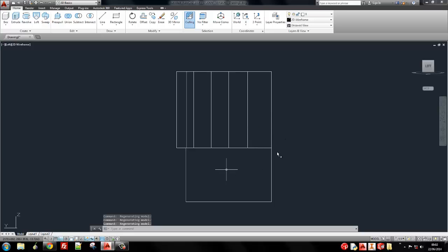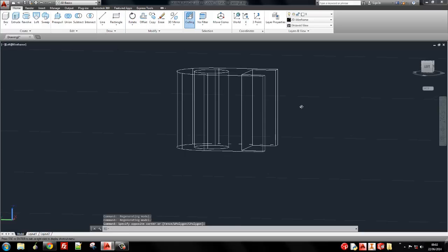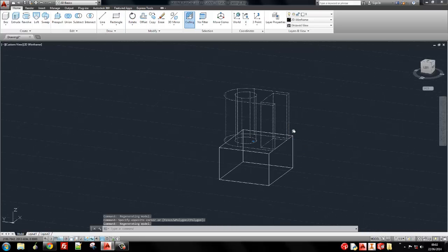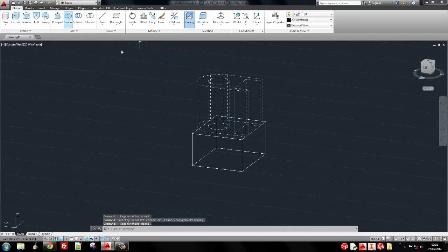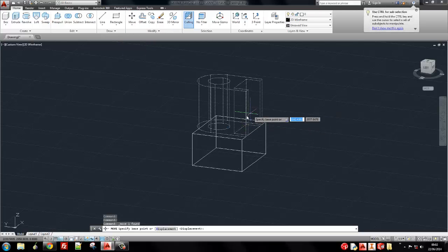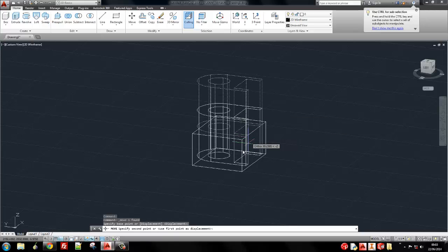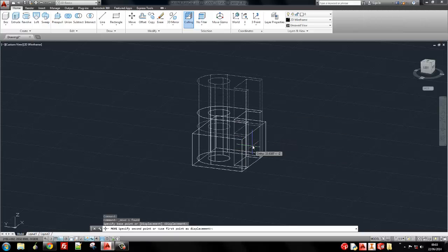In fact, they're sat completely opposite each other. So what I want to do now is position this object. So I'm going to orientate this around a little bit better so I can see what's going on, and I'm going to move it, if I can find the move button or M on the keyboard, and I'm going to find the midpoint of that, midpoint of that.